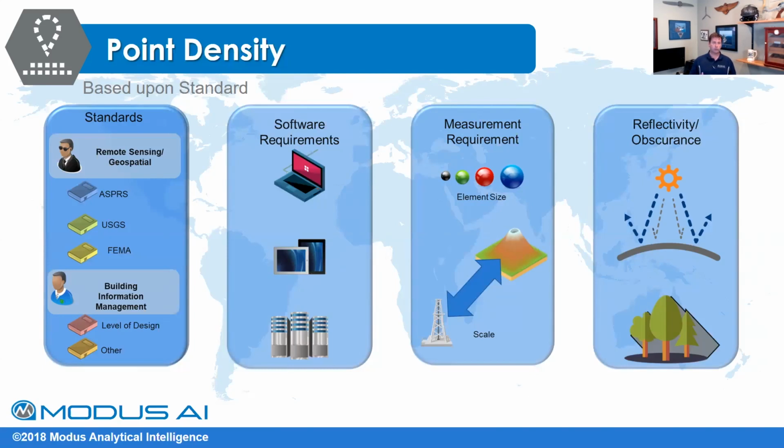So, bare earth, I may be pulling 350 points per meter squared, which is really good. But now if I get into vegetation, I'm down to 70 points per meter squared or 35 points per meter squared, depending on canopy. And if I'm trying to do limb size versus, let's say, a cable, a 3 centimeter limb will have the same reflectivity as a 1 centimeter cable. So, again, it comes down to what's your application to get the results that you need. We already talked about reflectivity.